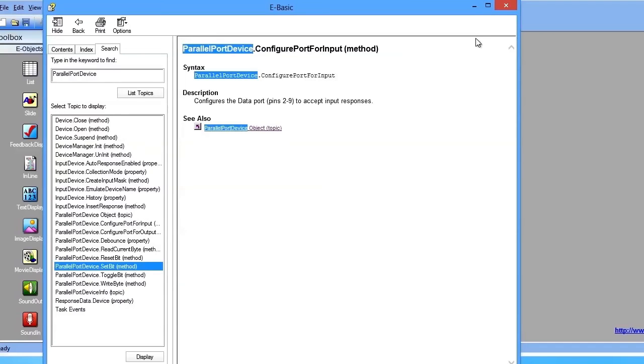You could also write your own Windows DLL. There are some users that have done that as well. Now, the address of your port can be found, as I mentioned, by selecting System from the Windows Control Panel and then going through the Device Manager. It's important to remember that if you are selecting the parallel port, you want to find the LPT or printer port. Then you click on the Properties button and the Resources tab. That will let you access the port that you need.